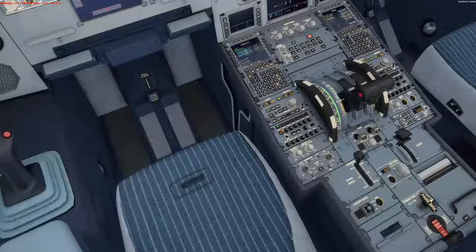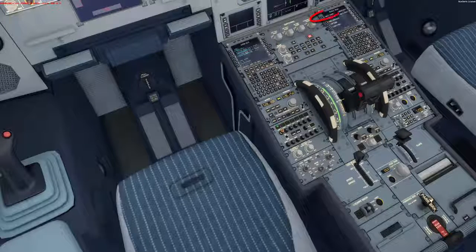As that's all happening, we can now do our first checklist. Now checklists are exactly that. You do the workflow, and then the checklist confirms that everything's been done. So to switch on the checklists, write CDU, checklist, switch on, and start the cockpit preparation. Okay, let's start with the cockpit preparation checklist.